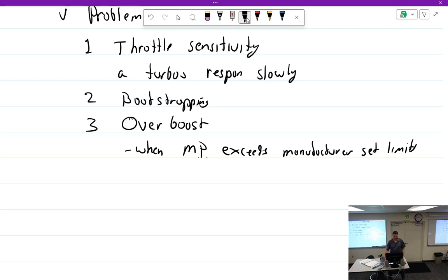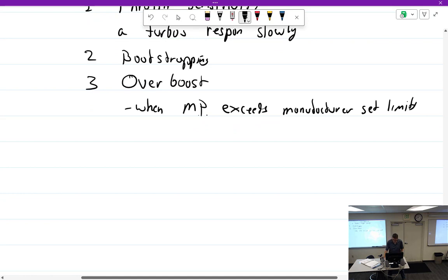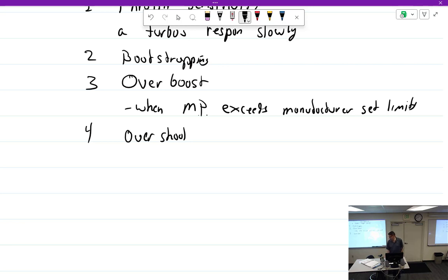Okay, good. I was going to say there's overboost and overshoot. I hope I talk about overshoot. So overboost can happen due to the time it takes for all these components to change. If you're not paying attention, it takes a while for the controllers to do their thing, and you just slam the throttle forward and, whoa, that was an overboost. So you have to watch out for overboost. And then there's overshoot. Overshoot is less. It's just a momentary overboost due to a lagging system. Overboost is when you actually go beyond what you're supposed to and it runs there for a while.